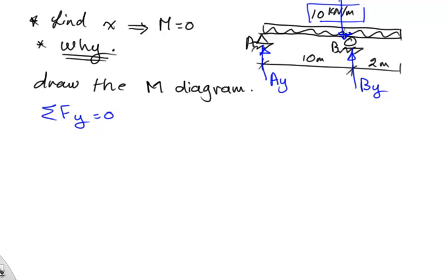That doesn't look like the middle, but anyway, you get the idea. The middle is half of the whole beam, which is 6, so the distance is 6 meters. And the value of this load should be 10 times the 12, which gives me 120 kilonewtons.